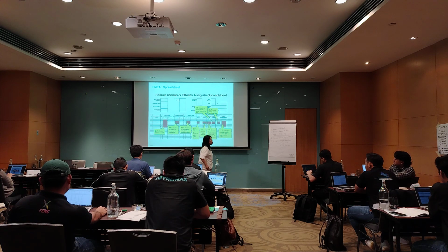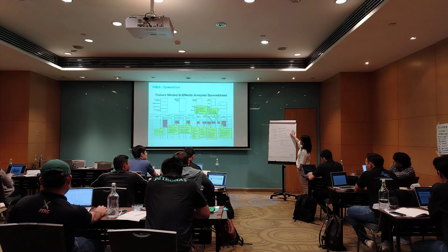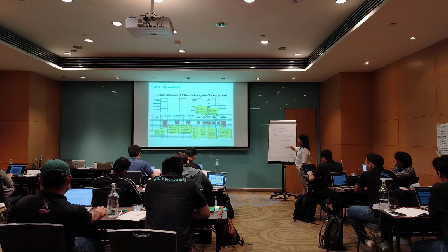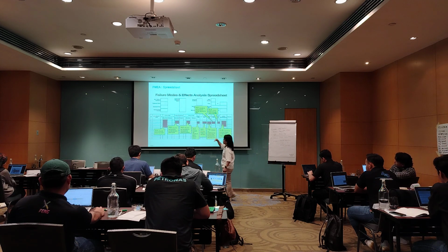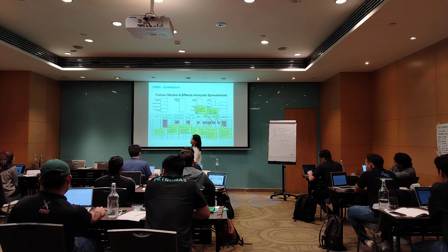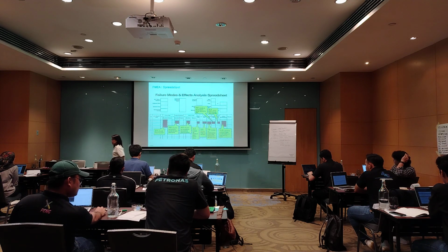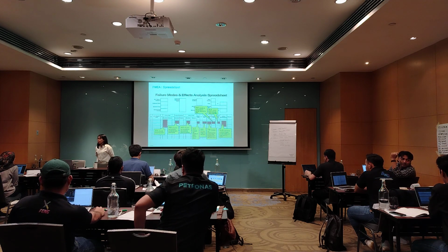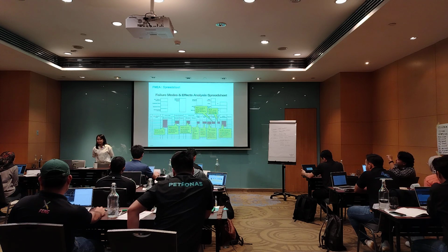What happens if the cooler is faulty, then the motor overheats? It can be one of them also. It can be many reasons. That's why in your FMEA you have many lines. You have many lines, then derive the different failure modes or different mechanisms. Yes, similar.